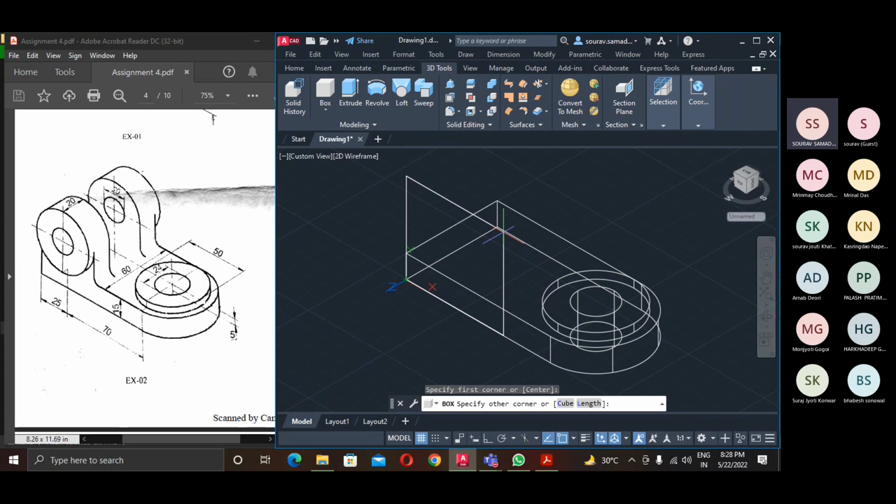Right now it's your front plane, but it's showing the top plane. Why? Because XY plane is your working plane. And we all know that our working plane, the XY plane, is actually the top plane. So the view cube automatically rotates, and after creation of my drawing, it will be automatically changed to the front direction.